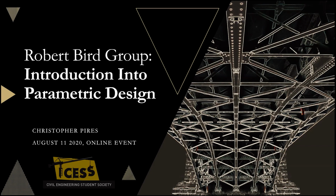So if you had a parametric design with an architectural build up zone as a parameter, and you already have the whole structural skeleton completed, and the architect changes that build-up zone by 10 mil, you can easily change your parameter and all your centerline models are updated instantly. That's a large advantage to using parametric design.